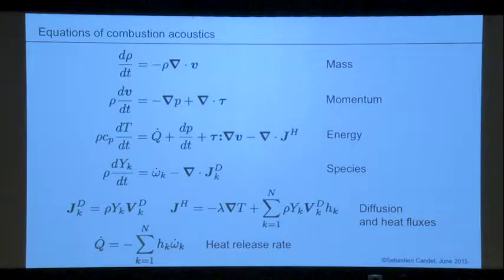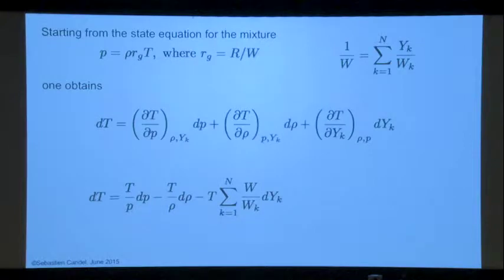So for example, you can say, this is the mass, so no problem. But now I'm going to include also the tensor, the viscous stress tensor. And I want to include also all the fluxes, the heat conduction fluxes. And then I know that combustion is a matter of changing the mass fractions due to the reaction rates. And I have also diffusion fluxes, and I have expressions for all that. And I want to keep everything there, and write down, nevertheless, acoustic equations. It is possible. It takes a little effort.